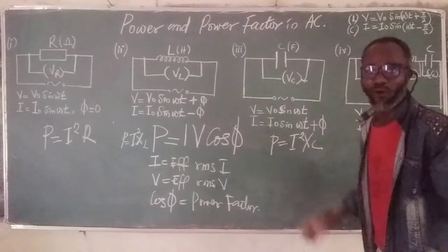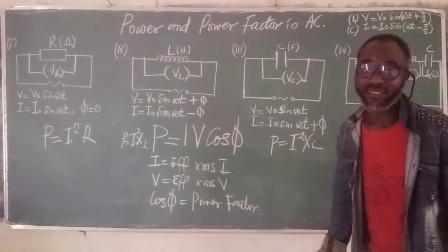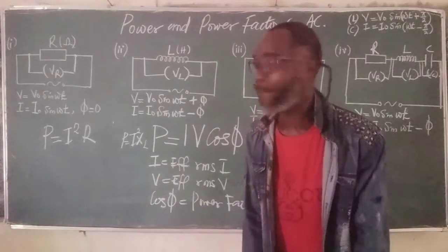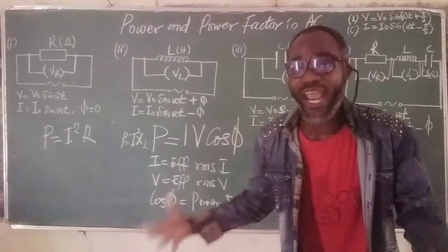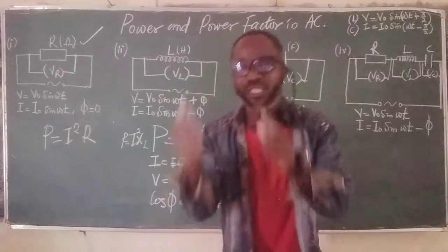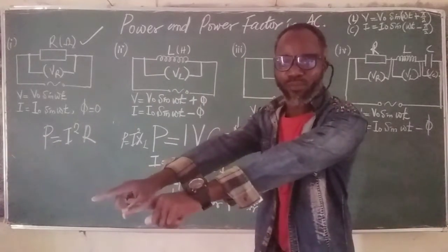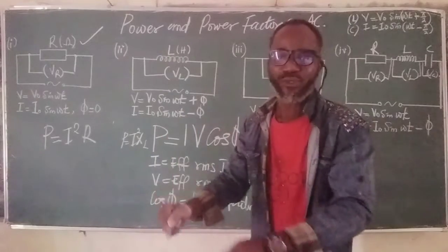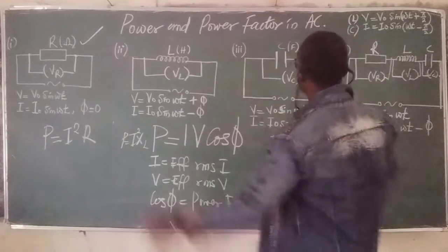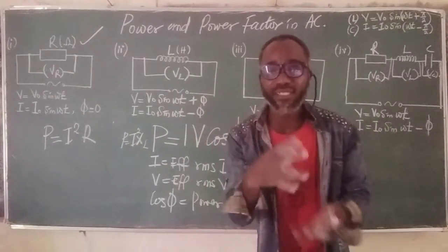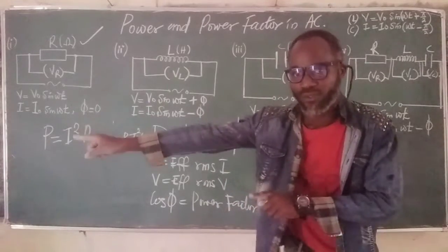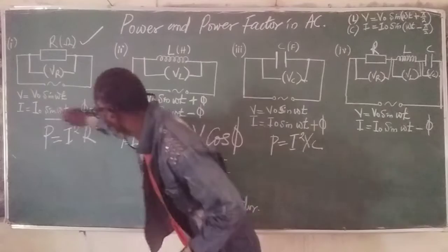But there is no need for all this. The reason is that the inductor does not consume any power. The capacitor does not consume any power. It is only the resistor that consumes the power, or the energy, that flows into an AC circuit. Take notes. So if you are given a question that contains these three components, and you are asked to find the power, just the power, not the power factor, use this.